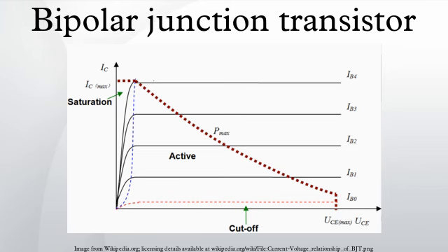The common base current gain is approximately the gain of current from emitter to collector in the forward active region. This ratio usually has a value close to unity, between 0.98 and 0.998. It is less than unity due to recombination of charge carriers as they cross the base region. Alpha and beta are more precisely related by the following identities.